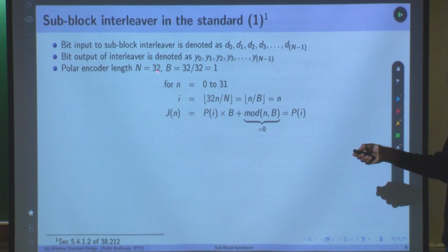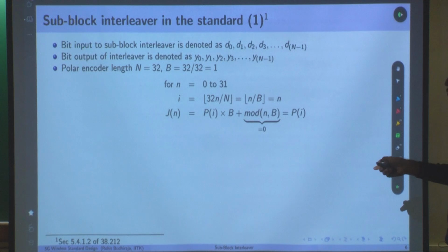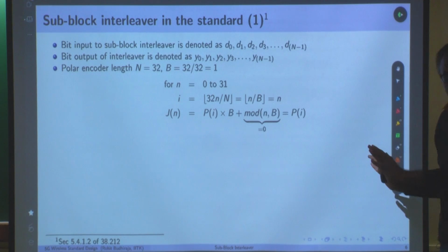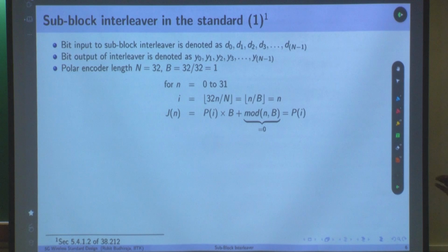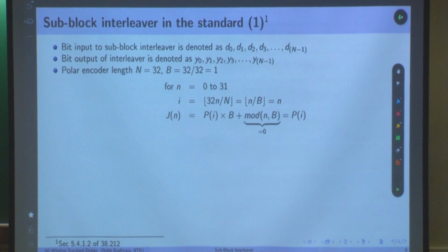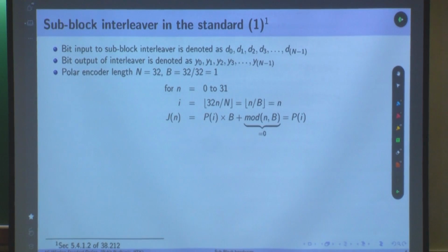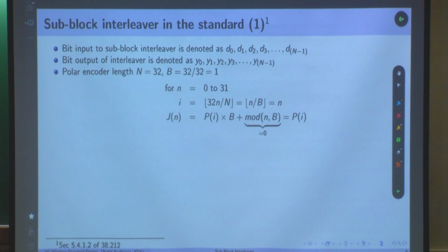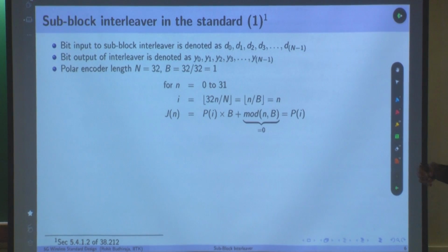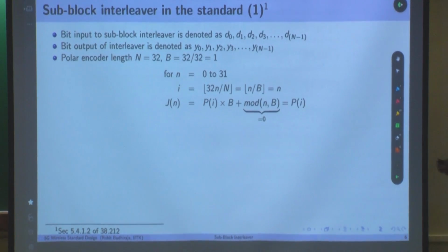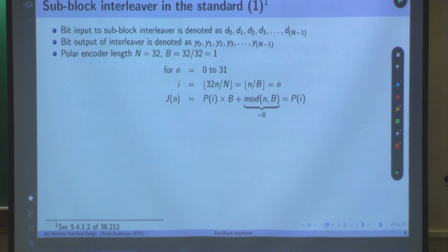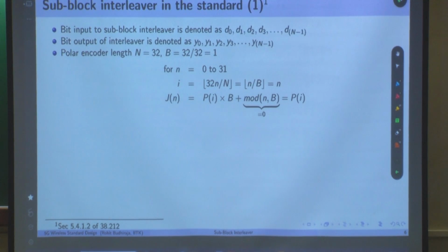You can do it for yourself, n is equal to 64, b becomes 2, and accordingly suitable indices are going to get generated, okay. And this is the interleaver pattern, that's all, okay. So here the mother interleaver pattern is 32, okay, right, and from there all other indices are being generated. We don't call that mother in this case, because what happens is you derive shorter sequences from it. Kid is smaller than mother, that's what it is, but here we are extending it, enhancing it, so we don't call that the mother pattern, okay.